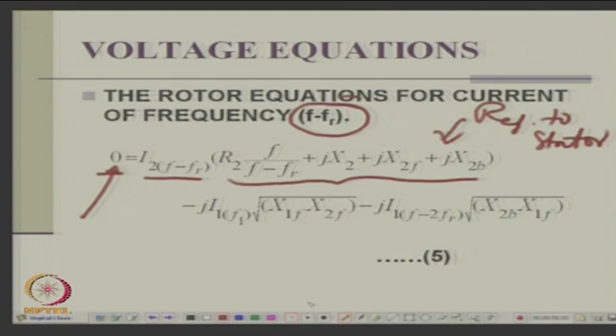So, these are all referred to stator frequency, all of them, right. So, all you do simply is you refer to stator frequency, all the reactances will be at the fundamental frequency, resistance is divided by that frequency. Okay. F over F minus Fr is your inverse of slip.